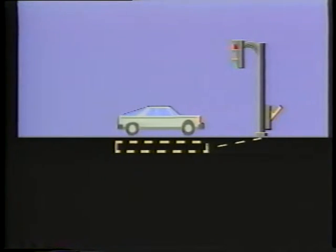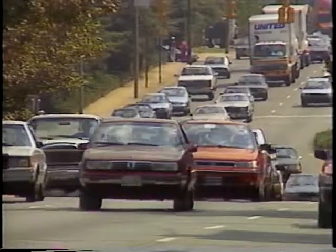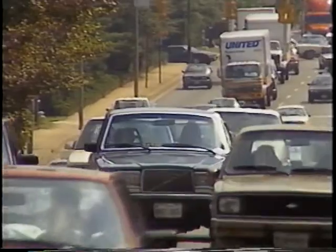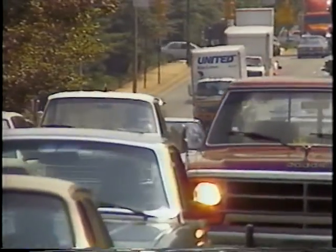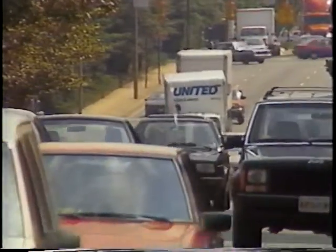This interval begins timing from the first call the controller receives from the cross street. When the signal is properly timed, with appropriately short passage time intervals, the maximum green time period will not consistently be reached unless the intersection is badly overloaded. Several actuated controllers are capable of providing 2 maximum intervals per phase, allowing more flexibility during peak traffic periods.